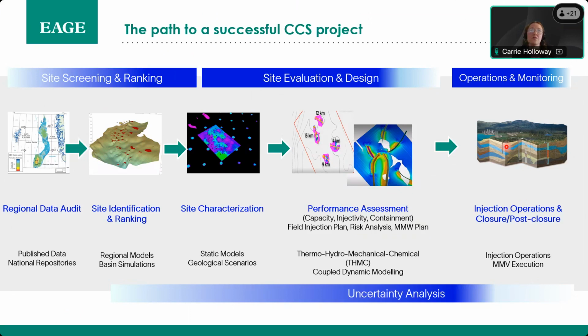They'll be also performing well design and deciding on an injection plan, etc. So once this is complete and FID has been taken, then the build phase starts. The next steps will then be moving towards operation. So first we'll do a baseline monitoring, and then during operations a continued monitoring. And usually planned injection is around 30 or so years.